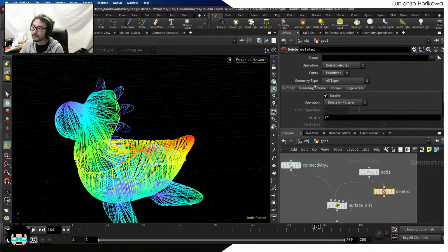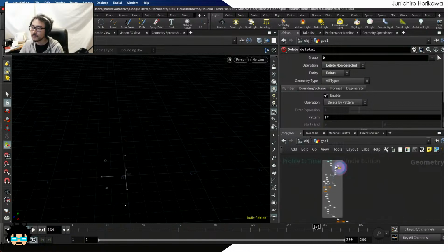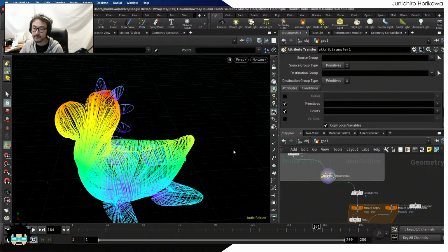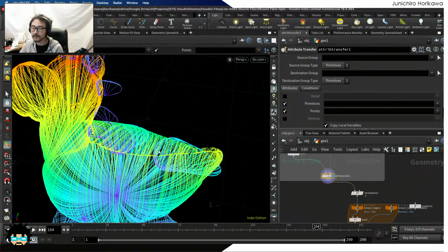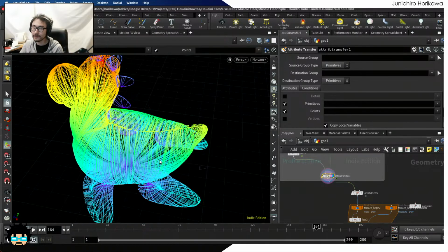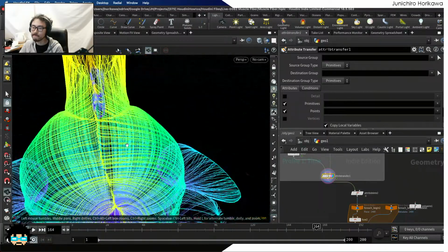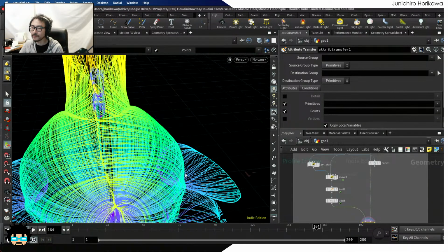Let's try. If you have a single point as a starting point, then the result you get should have fewer seams, but yeah, you still got those. That is because you are using the distance gradient. If you want to remove those seams, then one thing you could do is to blur the gradient vectors after you have retrieved them.